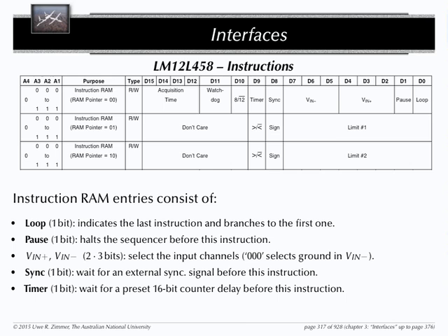The next 2 fields are telling from what I/O wires am I taking my input. Now, why do I have 2? I have a V in plus and a V in minus. Why do I have 2? Is that like exactly where they have a signal as well as the gain signal, and they subtract them to take out noise in the transmission?